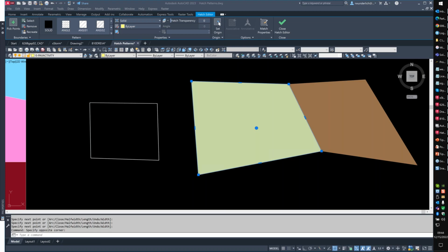And to be clear, using -purge in the Civil 3D template to remove all reg apps is a good thing. Yes, Cynthia, there are between 16 and 18 that always get put back into a Civil 3D drawing every time you open up Civil. As long as that list continuously remains under 20, you're in good shape.